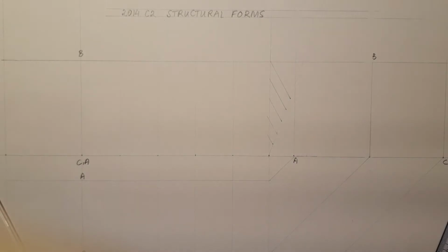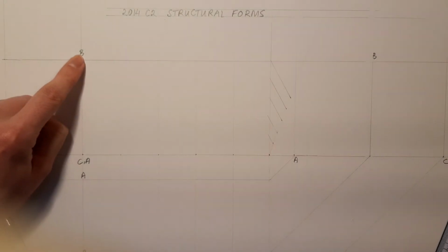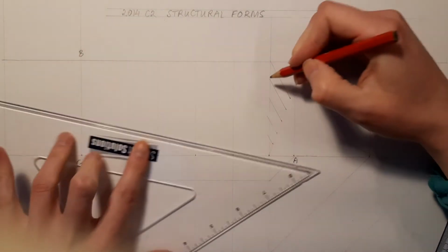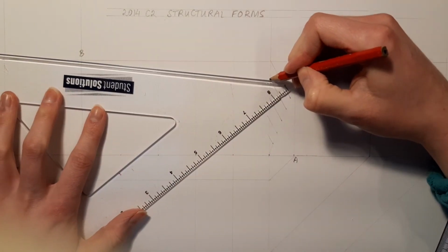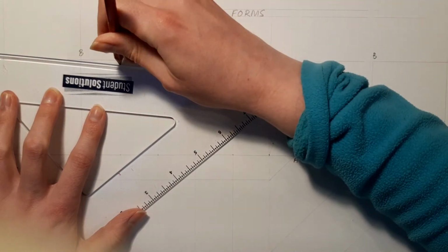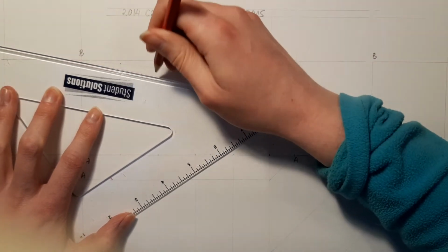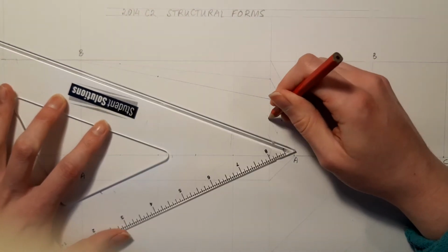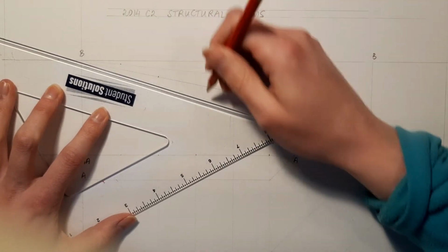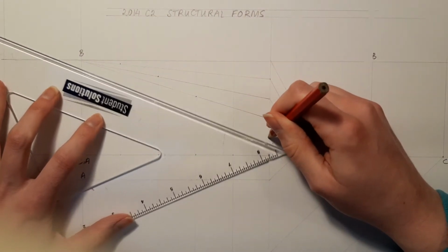At this stage, you should be well comfortable at doing a parabola. Every point is going to the vertex B. So bring the first line to B. Where it crosses on the first vertical distance is your first point. Second point to B. On the second line, you'll get to the second point. Third line, and so on.